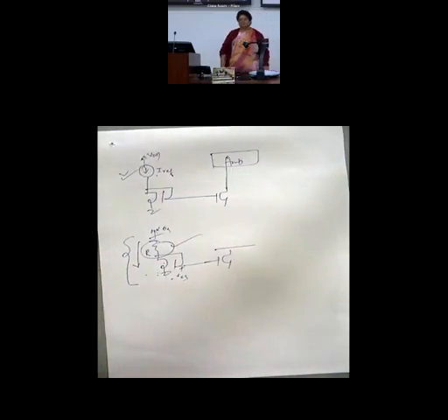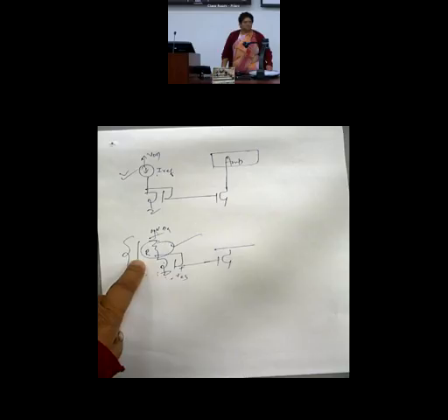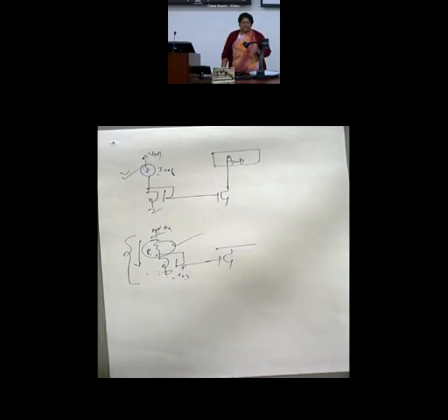We do not use it, because resistance will not ensure a constant IREF. Why? Because resistance changes with temperature. At the same time, if VDD fluctuates, the current through R will change. So it is prone to both VDD as well as temperature fluctuations. I should not use R, because when I say reference, this means a kind of standard current or standard voltage.